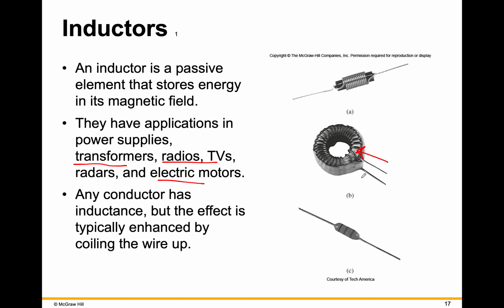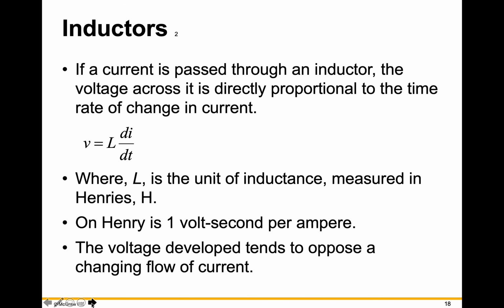Furthermore, when we start to talk about AC circuits, as soon as you introduce a magnetic core in here, its behavior varies with frequency as well. So the main difference between inductors and capacitors as far as you're concerned in this class is that the inductors we'll work with are linear, which means they would have to have an air core or a very, very limited operating range.